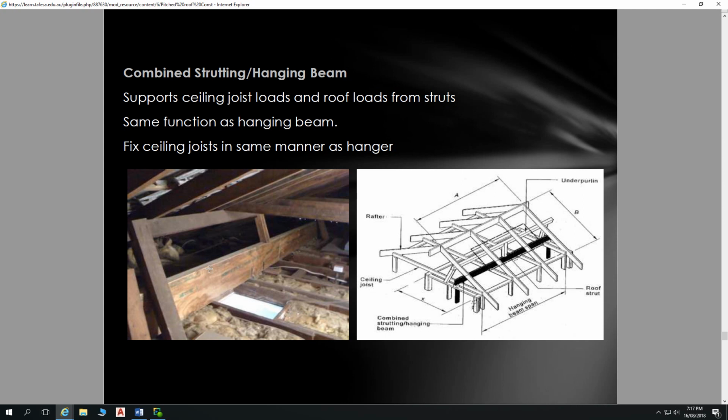When we make up these, that's called laminated veneer lumber. So we got all these veneers and laminate them together. It ends up being a stronger piece of wood per cross-sectional area than using a natural piece of timber from that same species. So if we take thin slices of pine and then glue them together with grain running this way and then grain running in a perpendicular fashion, etc., and glue them all together like that, you end up with a stronger piece of timber.